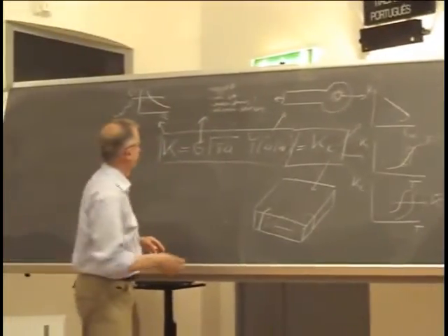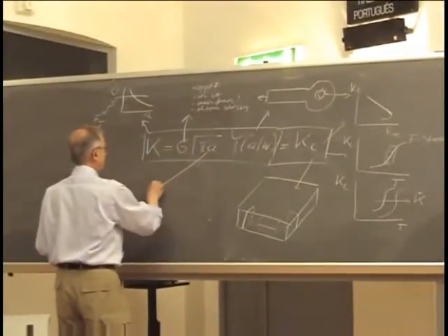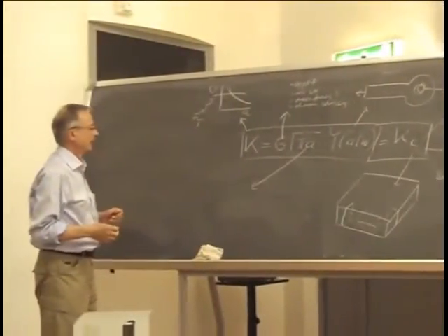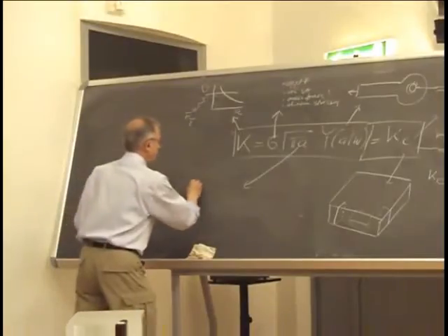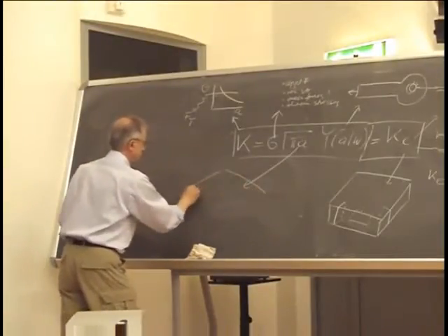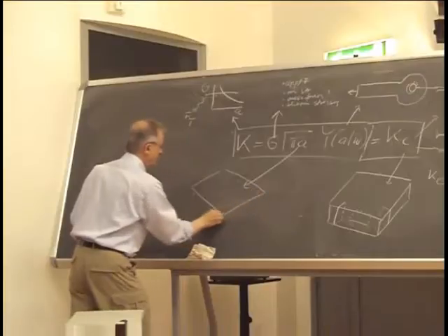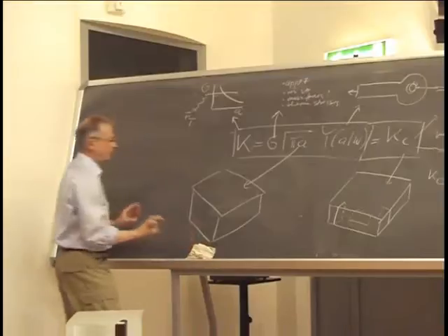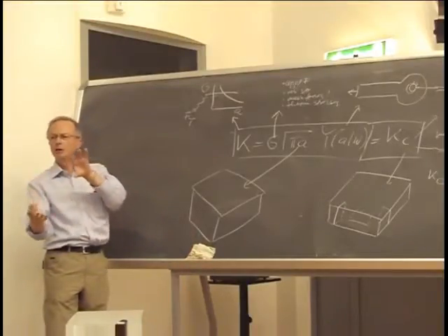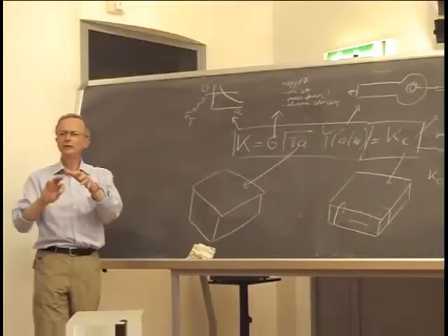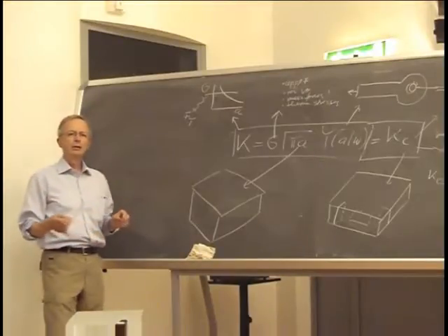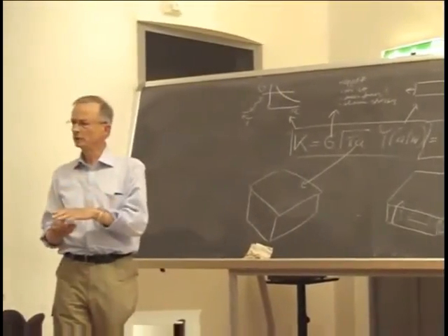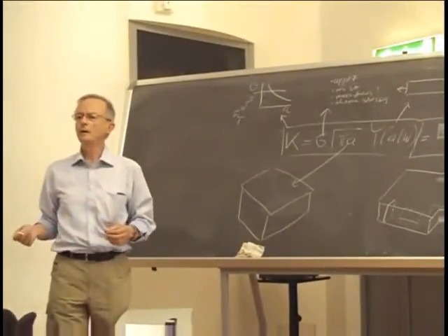So this should be enough for the material properties. The final thing is the crack size. No fracture mechanics without a crack. For example, you have a thick section and welded, maybe. You have a crack which has a 3-dimensional nature, a 3-dimensional plane lying somehow and somewhere, and your ultrasonics inspection gives you just a projection of the crack.